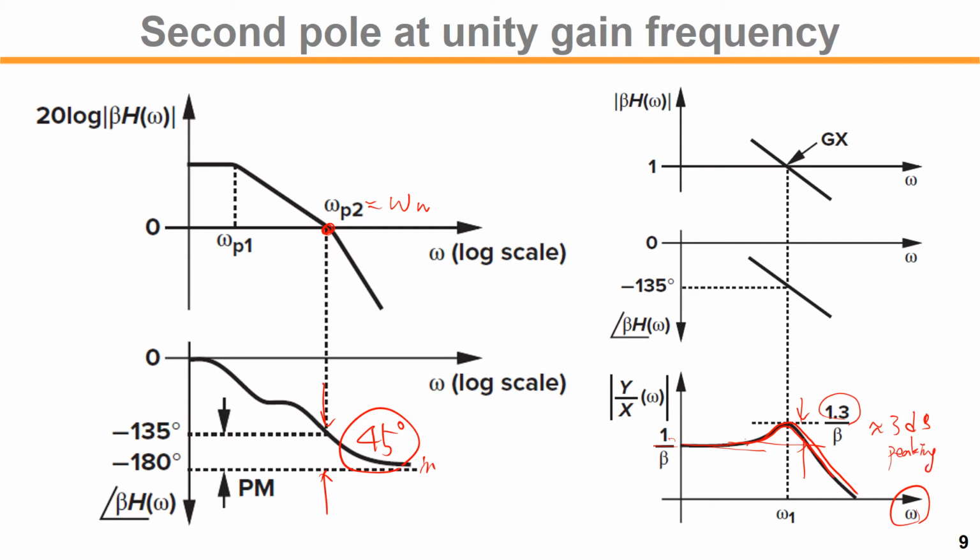So definitely, if you want smaller peaking, let's say 10% peaking is tolerable, for example, then you have to design the phase margin higher, right? We will see how exactly a peaking response is observed. We will see the detailed numbers in the rest of the slides.